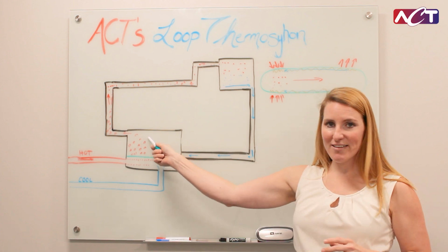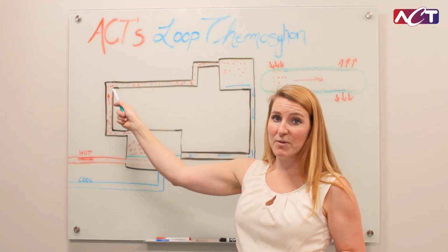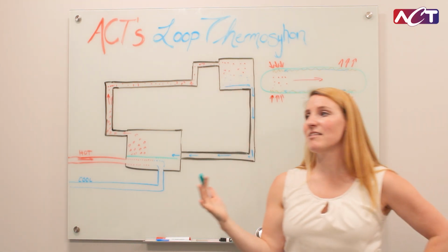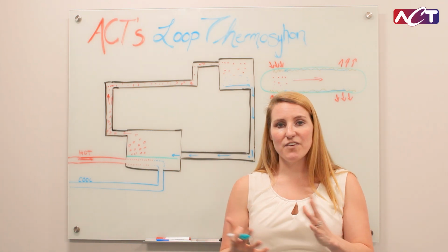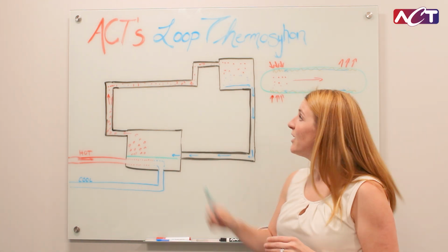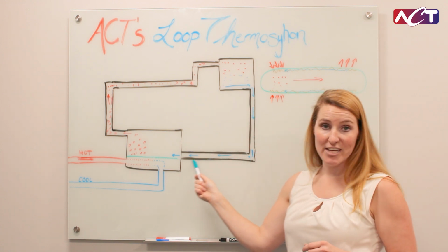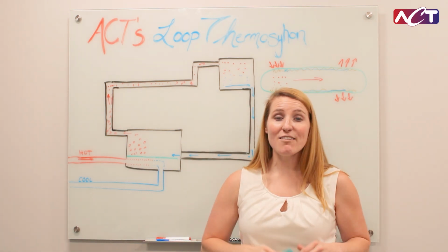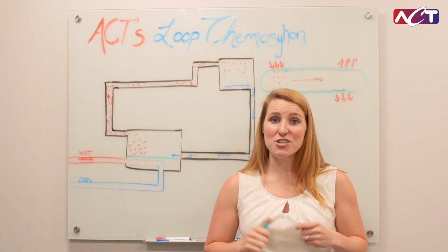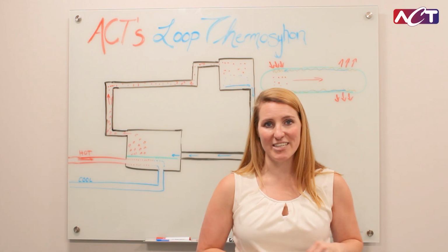Again, here, we're vaporizing at this evaporator plate. Then, moving through the tube, the vapor flows against gravity because of vapor pressure, going up to the condenser block. The condenser can be either a liquid-to-liquid interface or a liquid-to-air interface. Really anything, we can customize it for you. But the point is to condense the working fluid back to a liquid, and then the liquid returns via gravity to that hot spot. With these loop thermosyphons, we've been able to field upwards of 75 kilowatts of thermal heat transfer, making a very effective, very efficient, and also passive solution.